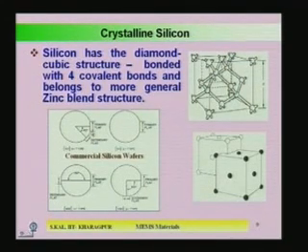Now, this is the center of this slice. So, from the center, with the primary flat and the secondary flat, the angle of 45 degrees is maintained. Now, if a primary flat and secondary flat are made like this, then this silicon slice is 111 n type. Similarly, if only this primary flat is there, then it is known as